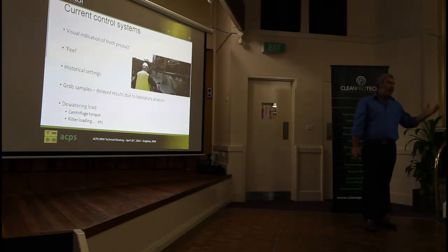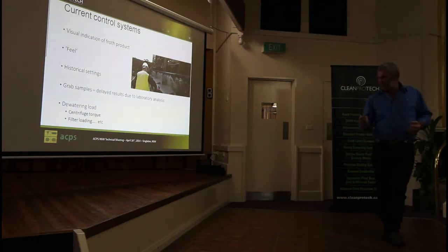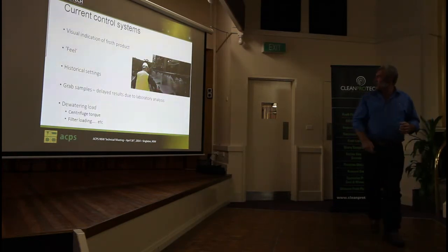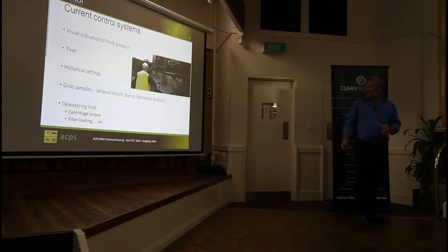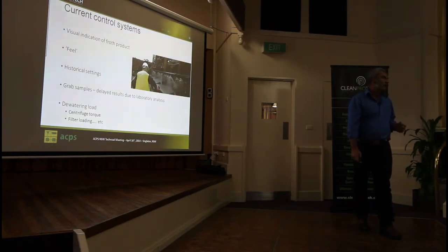Righto, how are the fine circuits currently controlled? What do we do? I mean, right there, we've probably got a piece of instrumentation that's controlling that flotation circuit. We do it by feel, by look, okay? By historical settings. We do have grab samples occasionally. We might get results back well after the whole situation has changed, the different feeders come in.